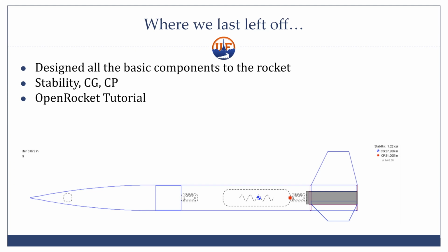This is largely dominated by the fins. Basically, if your fins are big enough, you're going to be stable enough. It's a little more difficult to calculate than just balancing the rocket, so it takes a little more analysis. But we have a really great simulator called OpenRocket to do that for you, so it shouldn't be an issue. In fact, I think OpenRocket is a really great resource for students and rocketeers in general, so definitely use it if you're interested in rocketry.